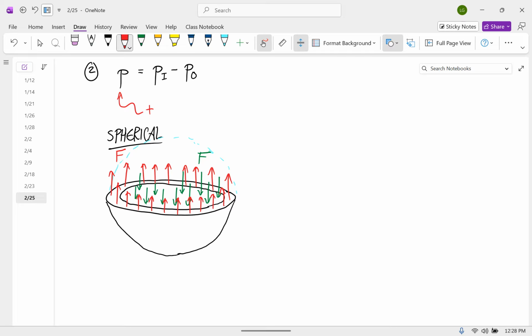That's a tricky key question, and that's what's going to allow us to do this calculation. So it's only really affecting the material; everything beyond that is just internal. Inside our free body, there's chaos going on, but remember with the free body diagram, all you're doing is trying to find the external forces. And these are all the external forces applied by that pressure.